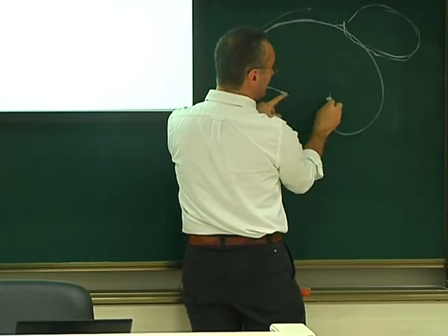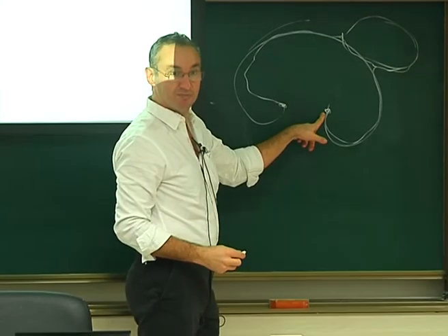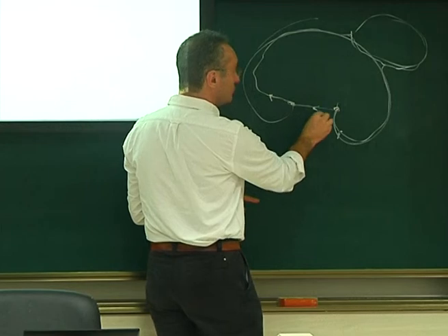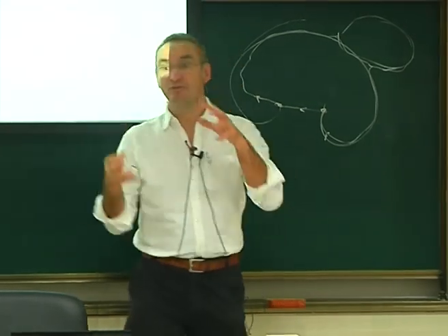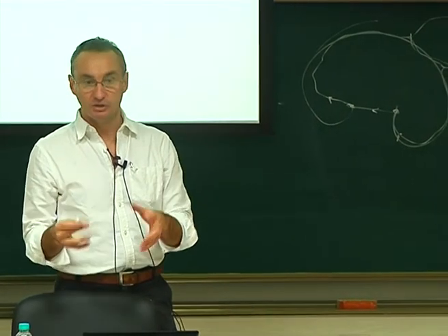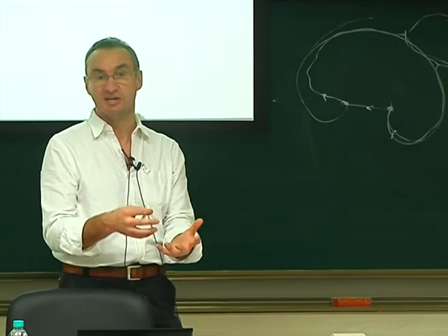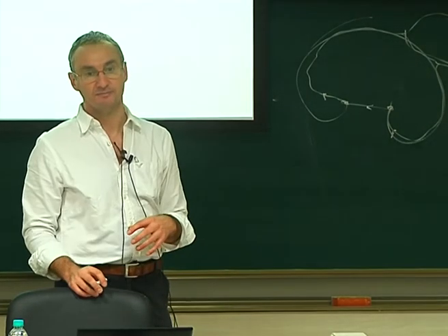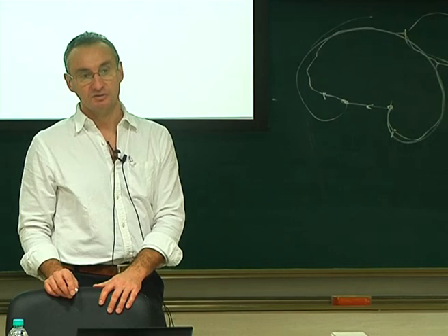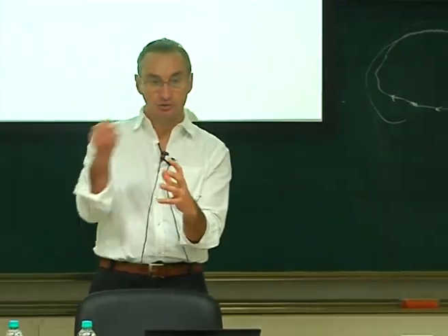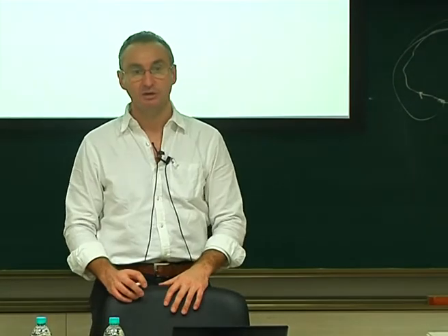Of course, it will still be pinned at this place. To remove those pinning points is very easy, because initially this dislocation was oriented that way. You just need to close it and let it relax again, and then you will have a nice skeleton. This skeleton has a name: we call it the Frank network. I think this skeleton is physical, something balanced energetically, and you can use it as a starting point for any DD simulation. It's more realistic. So this is one way to do it with the computer: you push to get a huge density, you relax, you close your loops to be sure you don't have pinning points anymore, and then you use that as a starting point for any simulation.